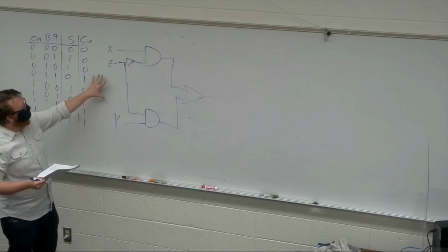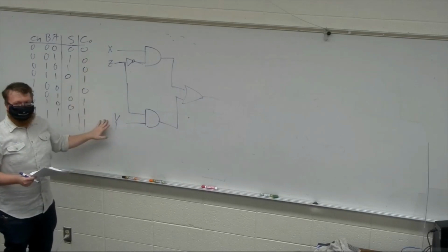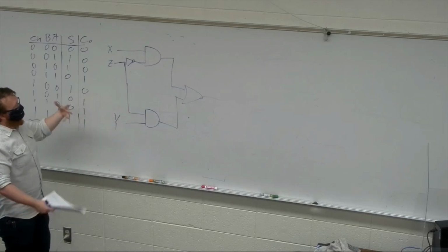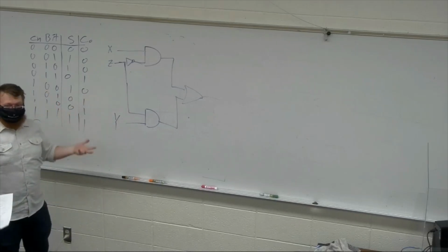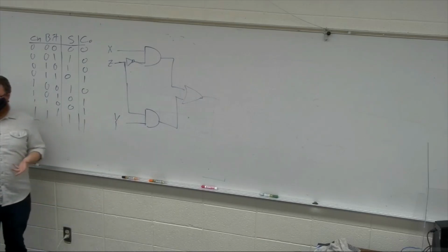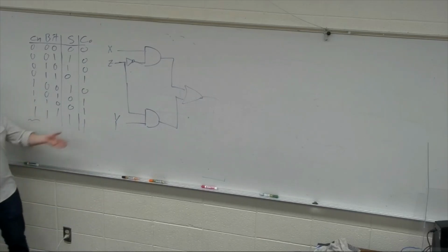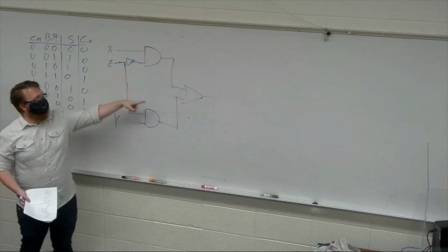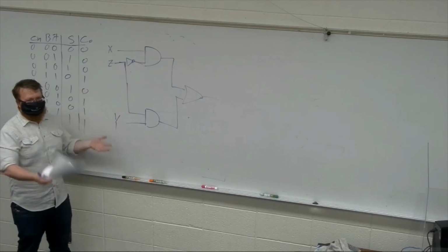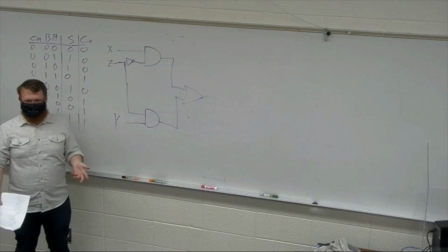So, we know X and Y have to be 1 in order for the gate to react. The next question is, does Z need to go 0 to 1 or 1 to 0? Well, that's harder to just look at. It ultimately doesn't matter, right? In this problem, there's a maximum of 3 gates at 10 nanoseconds each. It's 30 nanoseconds of drawing, which is 3 transitions, the worst case.